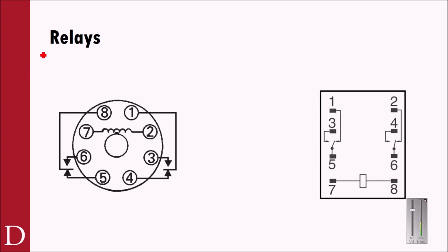It's very important for you to be able to look at a schematic diagram, whether that's a schematic diagram of a relay on a technical data sheet, or it's the schematic diagram of an elevator control circuit or something like that. And really what I'm looking for when it comes to relays is the ability to identify some key components. So if I look at this one as an example, this is a standard ice cube relay, has a round base on it. And it's got sets of contacts. A coil. It's going to have a set of normally open contacts and a set of normally closed contacts.